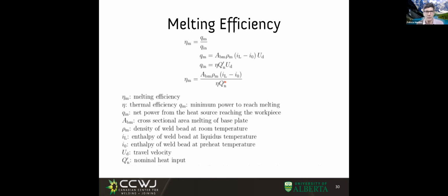And that's the reason why if we do oxyacetylene welding, we end up with horribly distorted parts with enormous heat affected zones. And if you do laser welding, the heat affected zone is so small that you need a microscope, right? Of course, there's slightly different prices in the two processes. This is the gist, right?